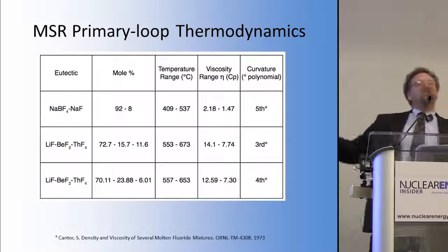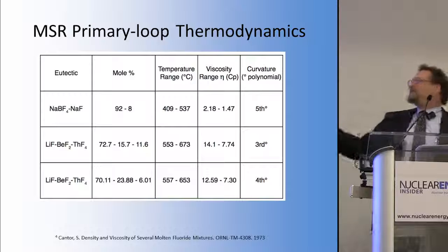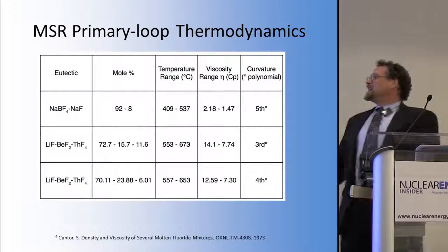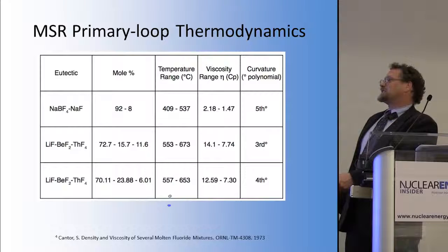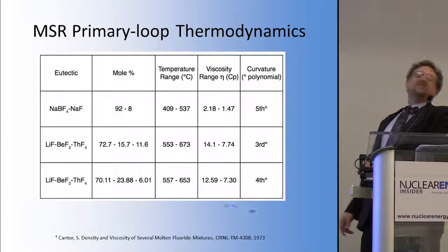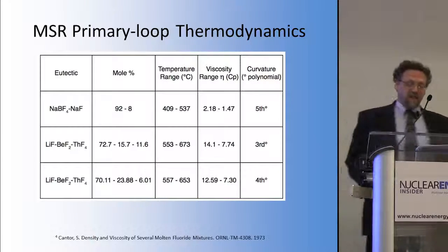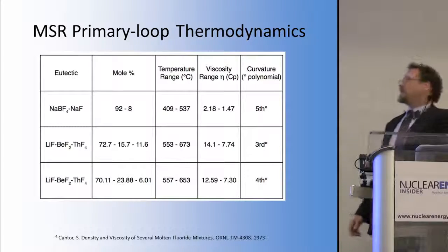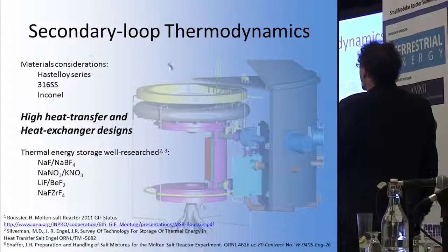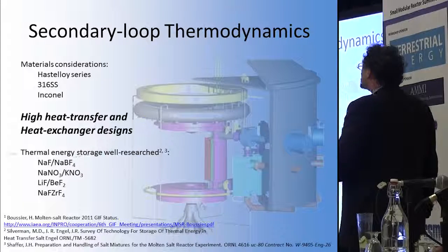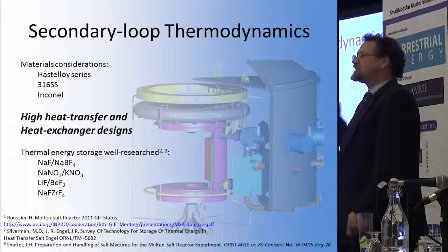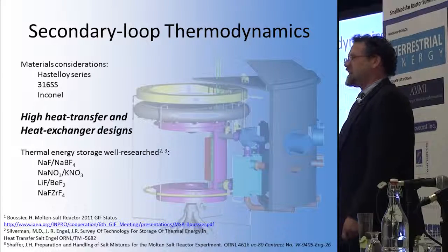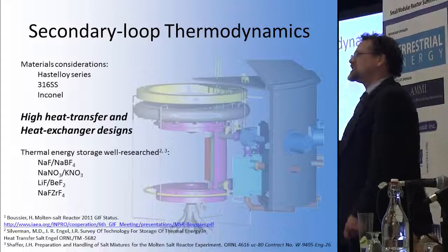If you looked at the actual curves, it would be remarkable. Right in the middle, for example, of this one, it dips down to 7.3, right around 600. And then bounces back up to 11 and back down to 7.3. And I will go into the reasons why that is so important. This would dramatically affect the geometry and the pore size and just about everything you could possibly think of with respect to a heat exchanger.